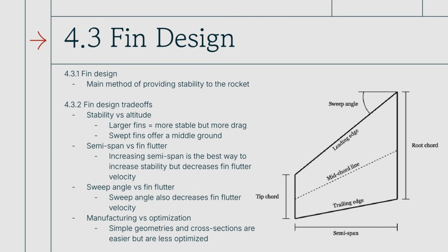Obviously, you don't want to design your fins so that you're exactly at the minimum stability you need to be safe. That's not a good idea because things always change and your simulations are almost never perfectly accurate. So you want to design with some buffer there. But typically you're going to be at odds with stability versus altitude.